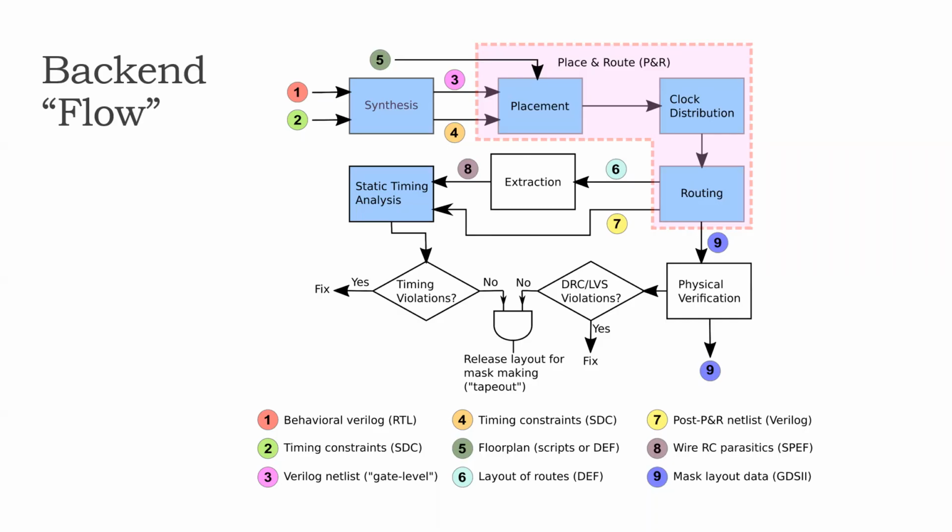So what I've not shown explicitly as an input in this block diagram are the standard cell data that every one of these tools needs. I've not shown that with arrows here. All the arrows are only showing the design data. You have to keep in mind that in addition to all these design inputs, every one of these blocks here also gets technology input, which is basically information on the standard cells and the standard cell library. And that information is either .lib or LEF or both.